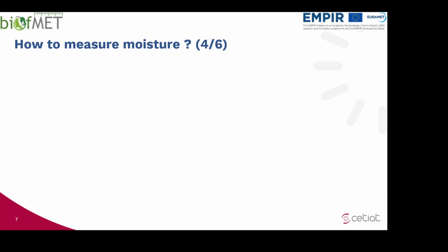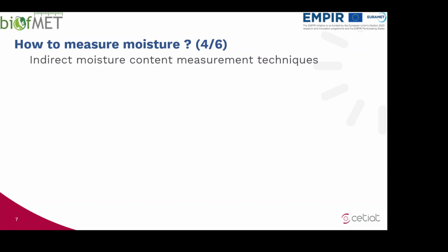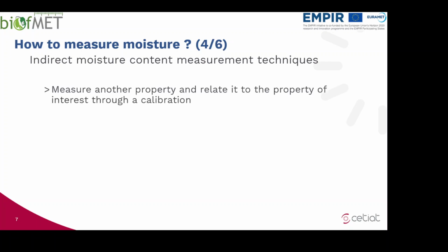Then, in metrology, indirect measurement techniques are used to measure a physical quantity of interest by measuring another property that is affected or sensitive to it. This means that the measurand being measured needs to be calibrated using reference or absolute measurement techniques. Indirect measurement techniques typically produce an electrical or other output on an arbitrary scale that can only be related to the measurand through calibration.